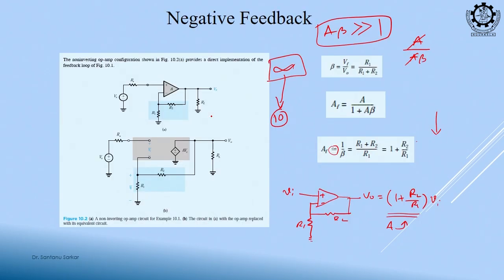So, you see this structure, this is my 2-port network of an amplifier that we did in the amplifier section. This is a model. So, this is my input side, this is my amplifier side A. This whole we will consider like a block of A, but if we draw the 2-port network, it will be like this. Input side is Vi, output is a dependent voltage source with A into Vi, that is it. And from the output, you are taking a path from the output to the input.